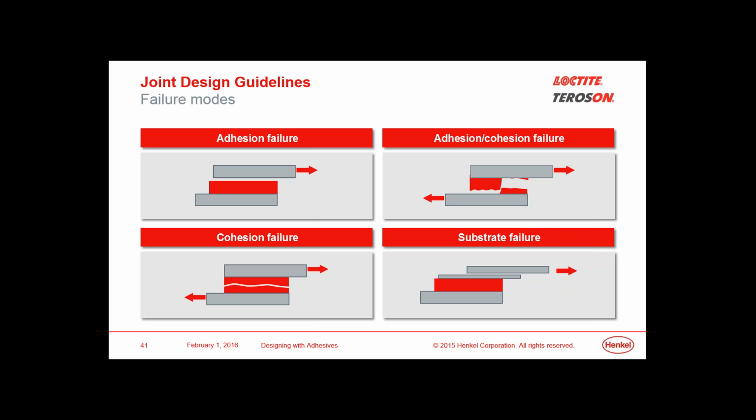There are, of course, some applications where the pieces themselves will actually crack as opposed to the adhesive, where the piece itself will break as opposed to the adhesive breaking. Common examples would be things like glass or paper and fabric or neoprene rubber or EPDM rubber, and some of the very easy to bond plastics. The adhesive strength is so high that you end up cracking and tearing apart the substrates themselves when you destructively test them. And of course, there can be a combination of adhesion and cohesive failure. However, you should be looking for a dominant cohesive failure with minor evidence of adhesion failure to the substrate.